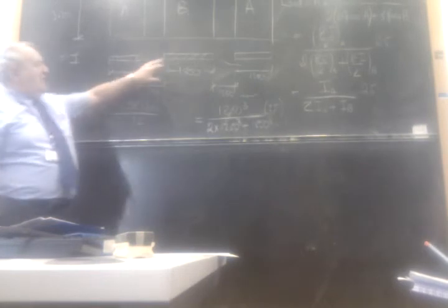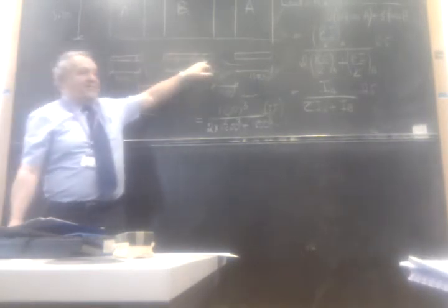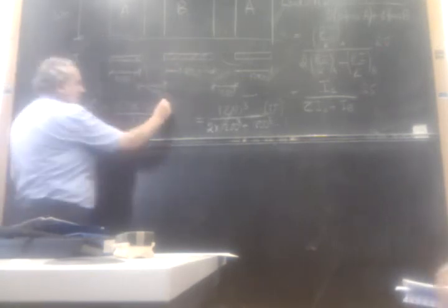What you'll find is obviously that is going to take more load because it's stiffer, because once you put an 1800 cubed in there, of course you're going to get something much bigger than that. But that would then give you the force in the wall. And it's obvious if you do the sums that it's going to be wall B, the middle one, that's critical.